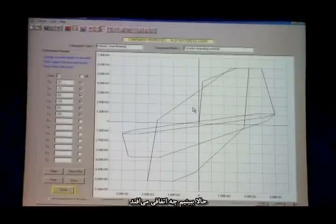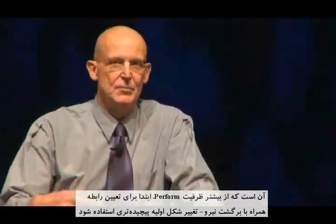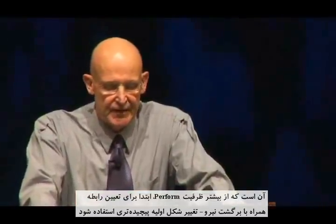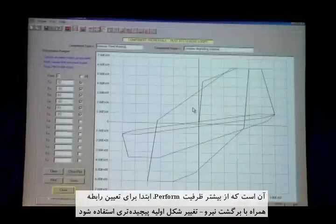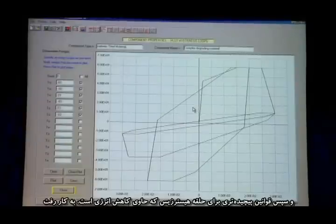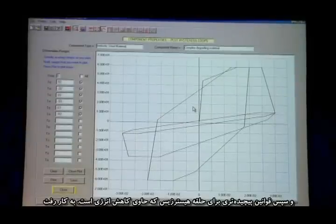What is happening here is that for this particular component, I've used more of the capabilities of Perform to specify, firstly, a more complicated basic FD relationship, the so-called backbone relationship, and then secondly, more complicated rules for the hysteresis loop, which involves some energy degradation.